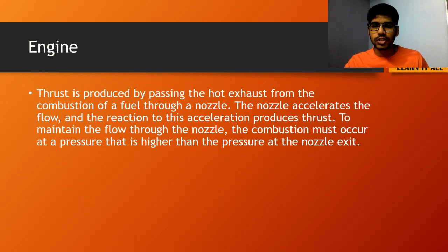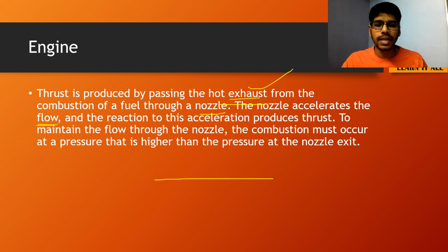The thrust is produced by passing the hot exhaust from the combustion of the fuel through the nozzle. So we already know that the nozzle accelerates the flow and the reaction to this acceleration produces thrust. Right? So whatever force was produced by the movement of the hot exhaust, obviously the reaction will be the acceleration.